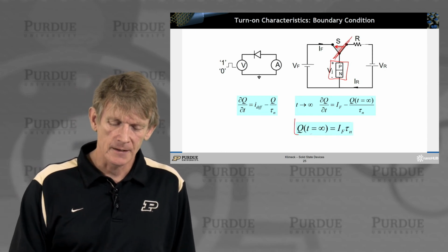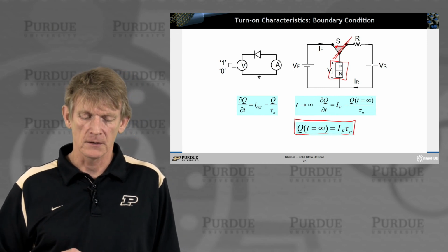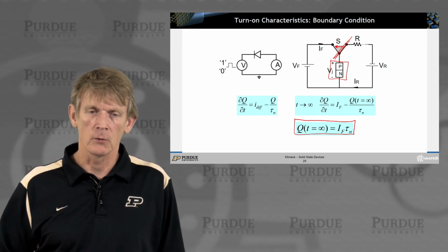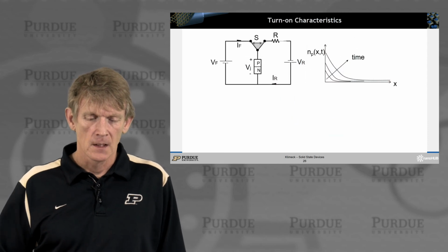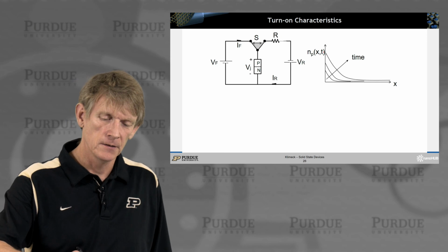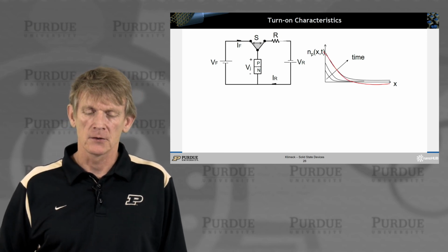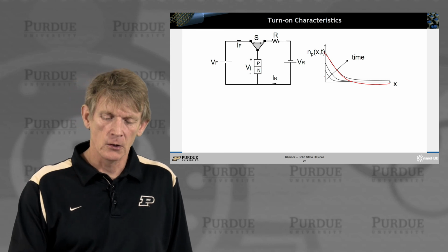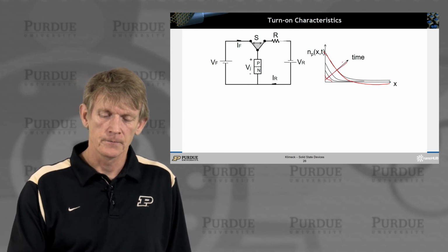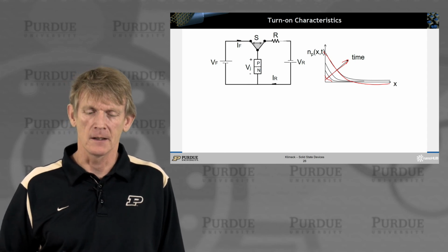The boundary condition at the end is when we're fully charged, that again we have a forward bias current that gives us the charge that we want to reach. Okay, so the final charge we want to reach will be looking something like this, right? That we are inducing into the device again, and it'll grow in time like this. Okay, so there will be no minority carriers, and we're beginning to inject them in time.